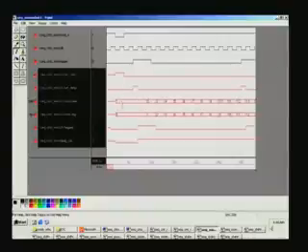Otherwise there is no difference between the two. You have a trigger P also, which holds the previous trigger value. The current trigger value is here, and whatever is the current trigger value will be pushed as the previous trigger value for further processing, namely to find the rising edge of this trigger. That is the reason why we preserve it.